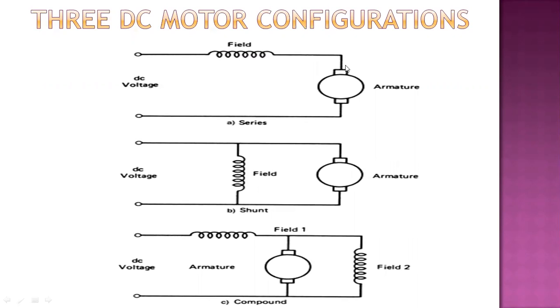The characteristics of a DC motor with a field, you can consider like the first one, that is a series DC motor or series field. This motor has large starting torque but is difficult to speed control. So it is good in applications for starting heavy, non-mobile loads and where speed control is not important, such as for a quick opening valve. For that type, the series field will be used. The next one we are having is the shunt one.